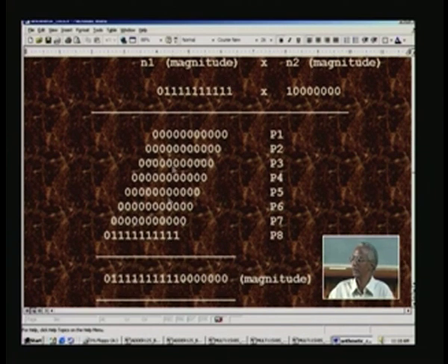Now how do we compute the multiplication in the usual way? We are going to go into the algorithm now. When we take two numbers, we take the first bit and multiply all of this and put it here. Here it happens to be all zeros because we are multiplying with 0, and out comes 0. So is the case for all other 0 bits, and every time we shift by 1. This is what you do while hand computing, and the final bit is 1, therefore the same gets duplicated here, with of course a 1 bit shift. In the usual fashion, you just add, bit by bit along with the carry, and finally this will be the result as far as the magnitude is concerned.